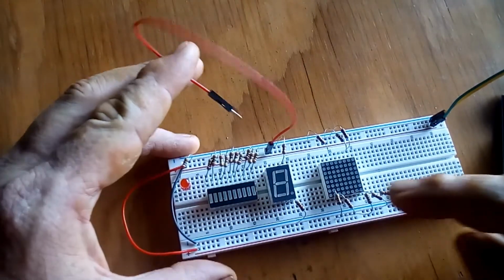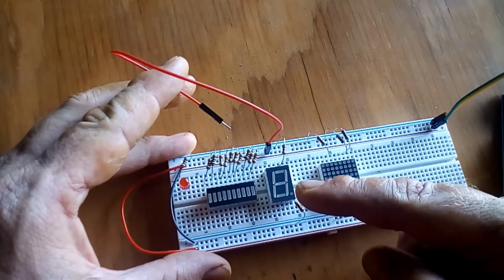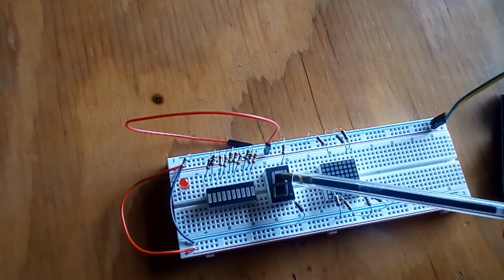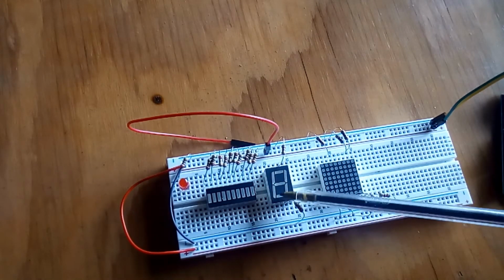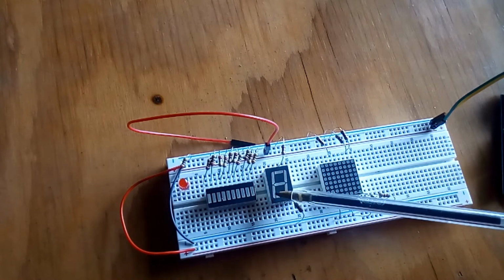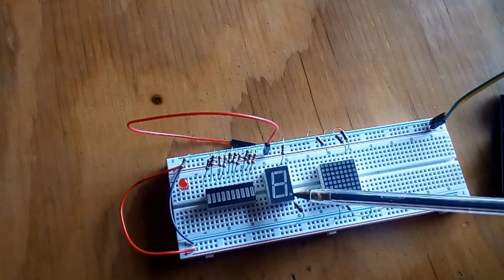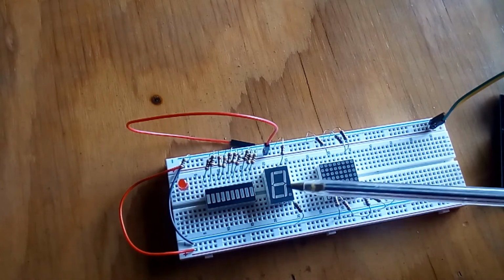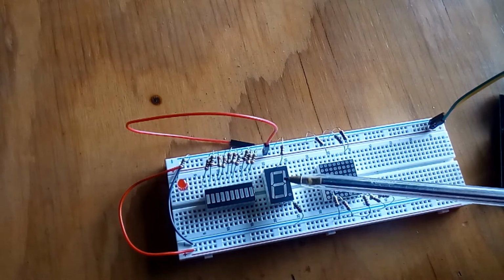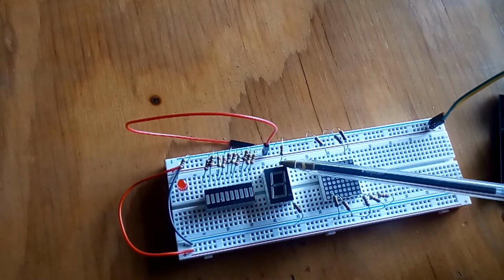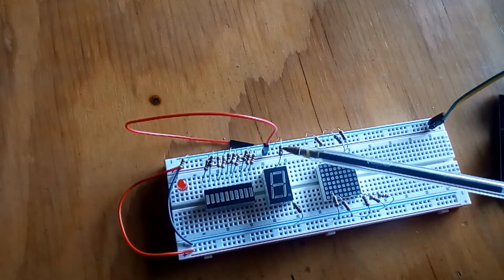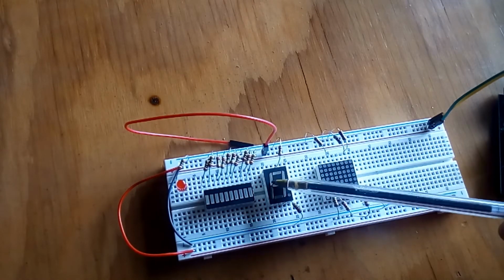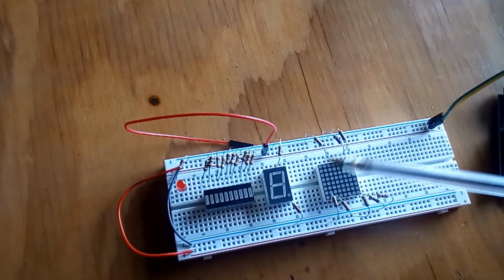The next one here is a 7-segment LED. So, like the name implies, 7 separate LEDs to make a number, right? These 3 down the middle, and then these over here. And there's actually an 8th LED on most of them, the little dot in case we need a decimal point afterwards. So on this one that I hooked up, there's 2 common cathodes, so I have those coming back to ground, and then each one of these LEDs gets its own anode.